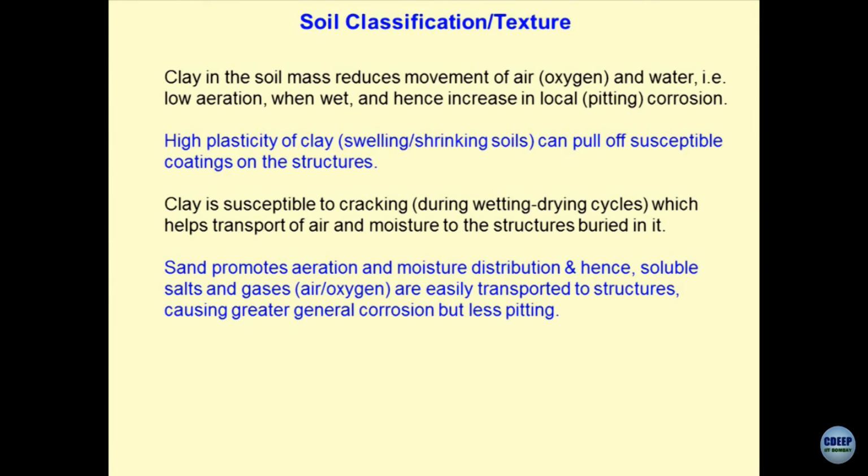So, imagine soon after burying the utility, the entire backfill cracks. Clear? Very unwanted situation. So, these types of situations have to be avoided. So, clays which have minerals where wetting and drying is important, or which are very active as far as wetting and drying is concerned, you have to be careful when you use them.